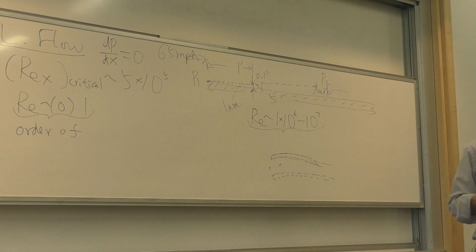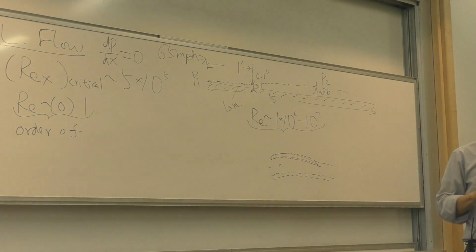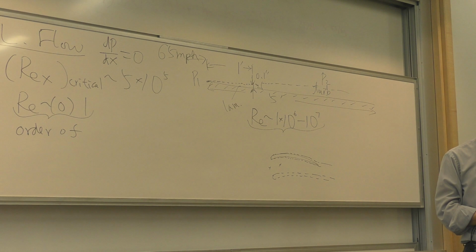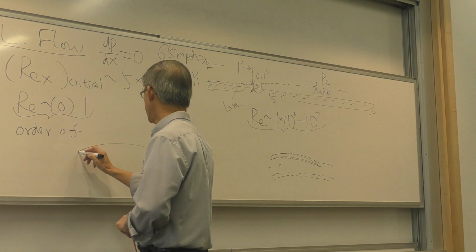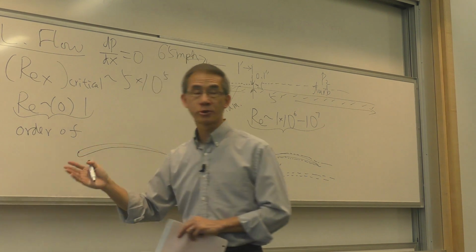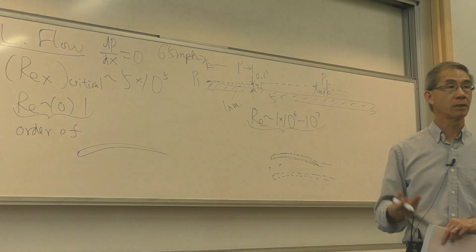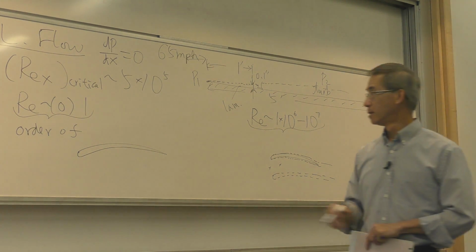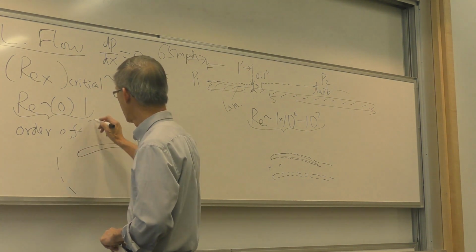And with that said, you don't have a thin, small boundary layer anymore. That concept breaks down. So with the same airfoil, whether the size is much smaller or the velocity is much lower so that the Reynolds number is small, this so-called boundary layer becomes almost the entire flow field.